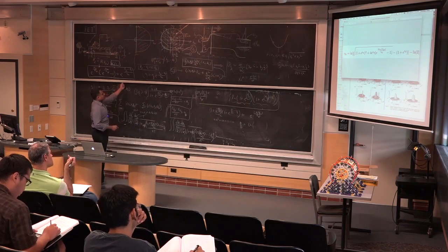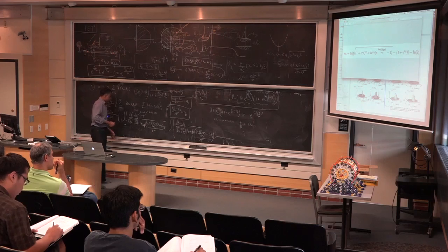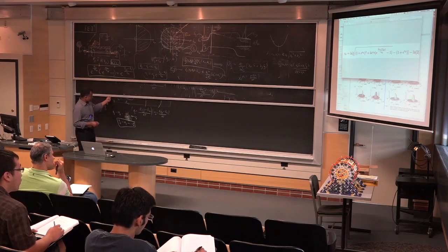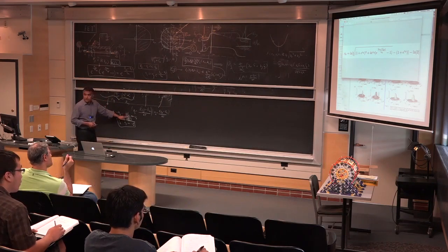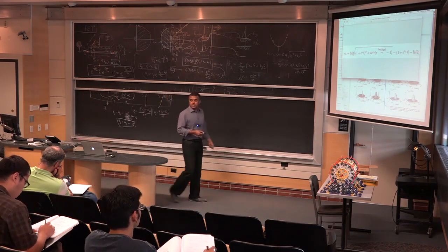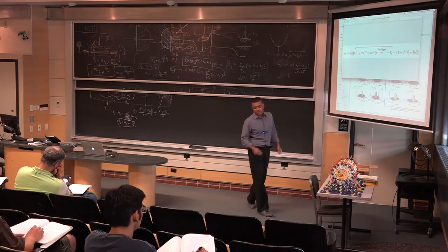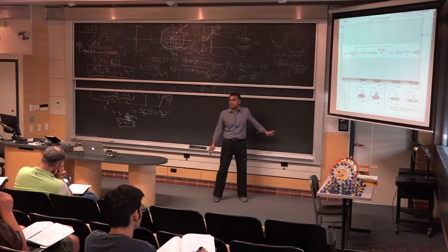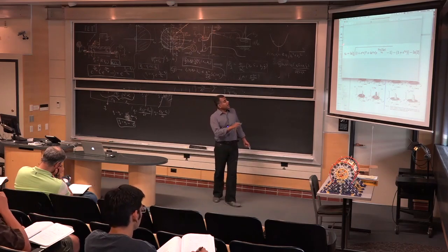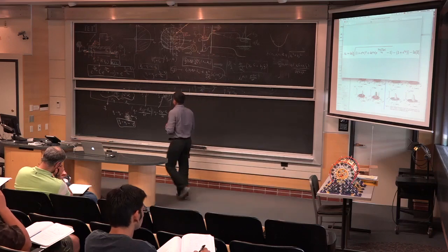Where did we define it? It's your drain voltage over kT, right? So VDS over thermal voltage. So once you know you have applied 0.2 volts on the drain, you know what that is, right? So VD is a number. So it depends on that. There's a square. This is just a solution of that quadratic equation we just wrote. This is a solution. And once you define what is the gate voltage, the whole game now is go back here,